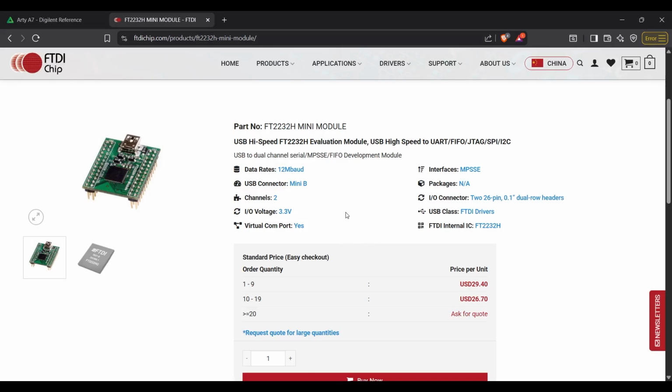And what we are going to do now is see how we can achieve full USB 2 speed. We are going to see we need to use FIFO mode in the IC, synchronous FIFO mode, which essentially has 8 bits of data, a clock which is a 60 megahertz clock, plus some handshakes that are used for the FPGA to communicate with FT2232 to read or write data.